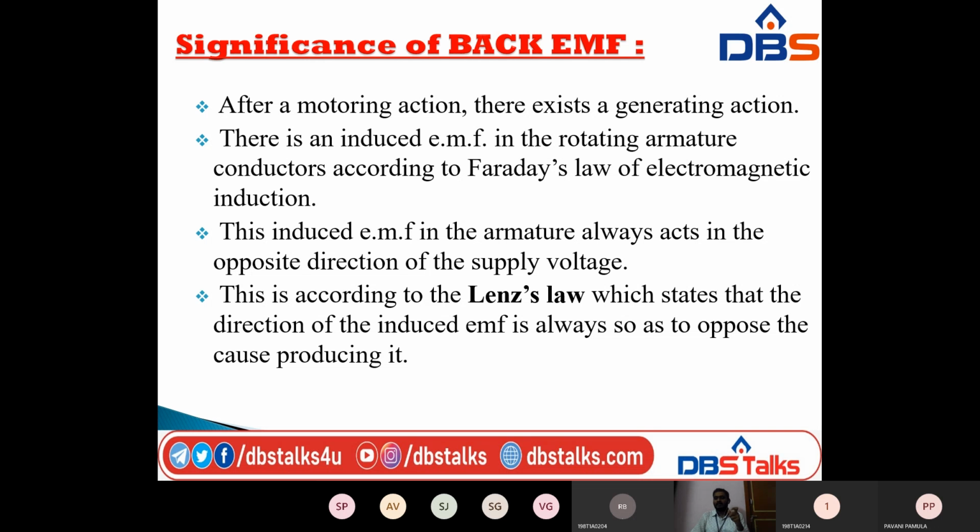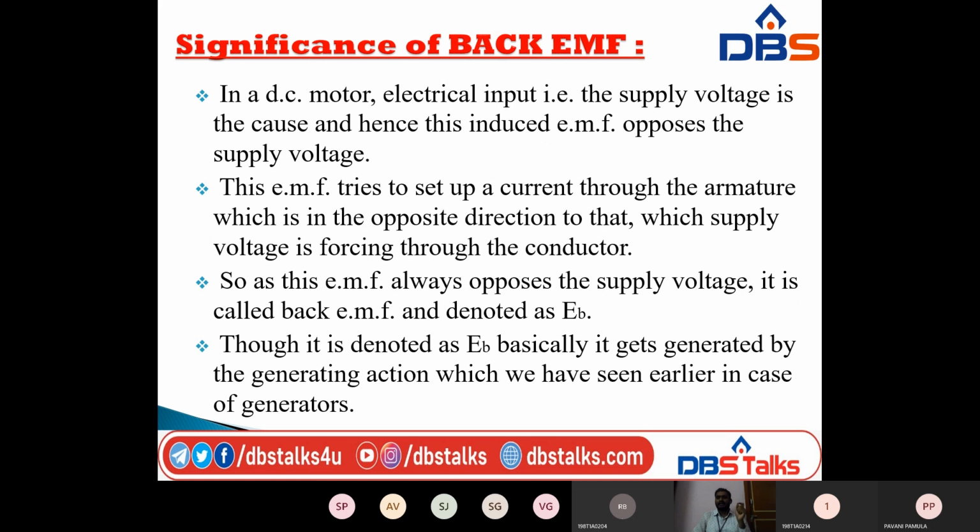So the supply voltage is the cause, and the induced EMF is the effect. This is according to Lenz's law, which states that the direction of the induced EMF is always opposite to the cause producing it. So in a DC motor, the electrical input, that is the supply voltage, is the cause, and hence the induced EMF always opposes the supply voltage. That is the statement of Lenz's law.